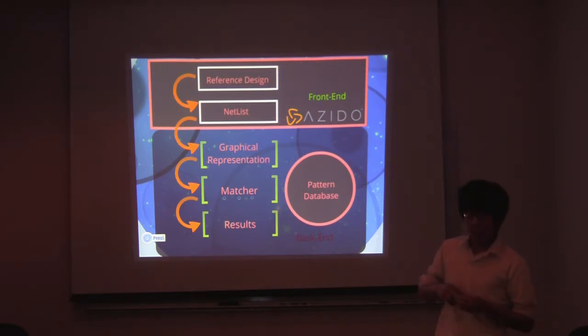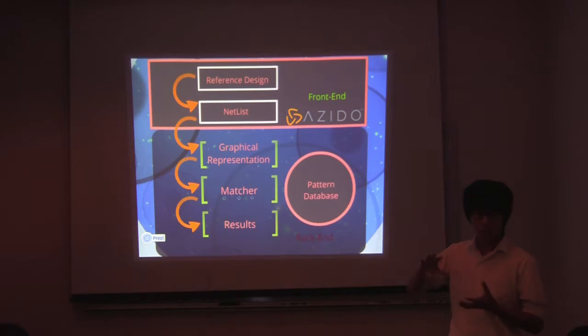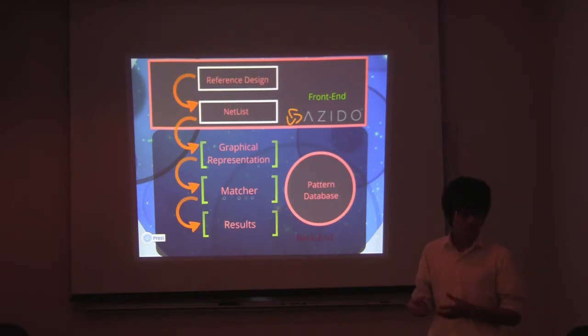Well, I meant that, the idea is that because designing for FPGAs the turnaround isn't as high, but I was assuming that I was going with more of when you're downloading the entire design onto the board and testing it that way. However, the netlist doesn't require all that place and route step when synthesizing for the board. So all I'm interested in is just the netlist of the circuit.